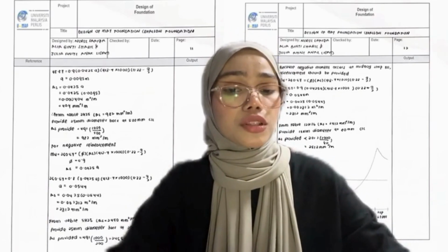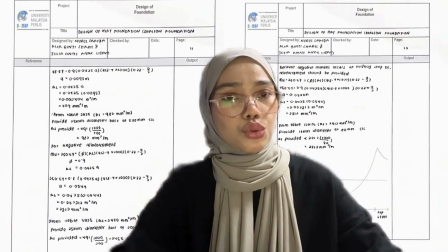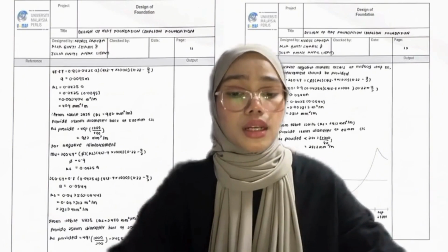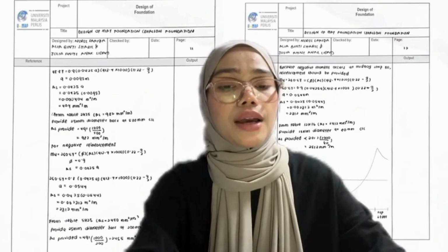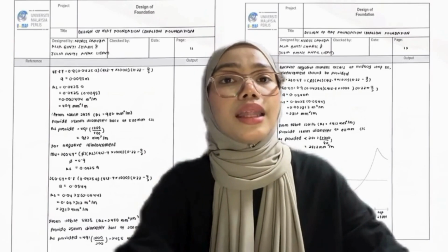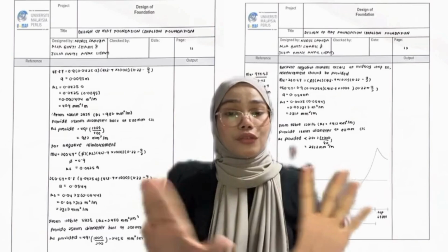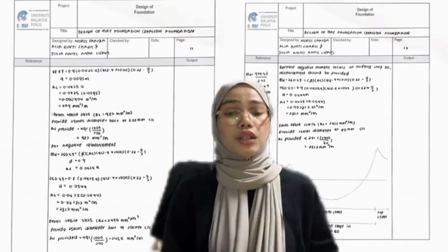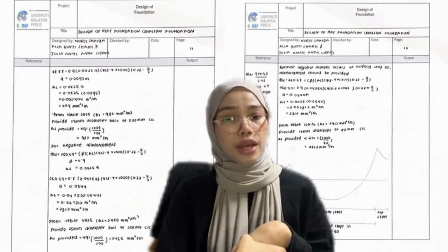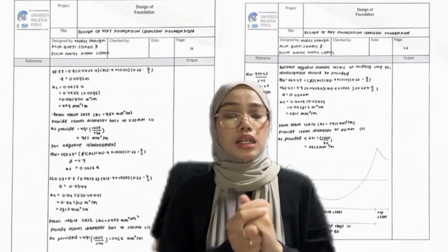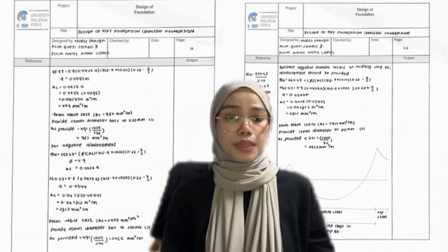For the negative reinforcement, As we got is 2312 millimeter square per meter, and from the table we got 2450. Because the negative moment occurs at the middle strip BD, reinforcement should be provided for Mu, and As is equal to 2312 millimeter square per meter.